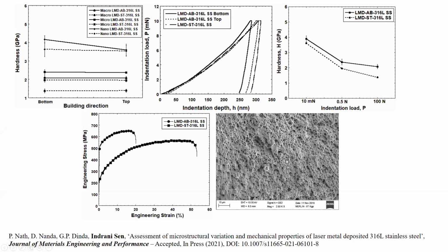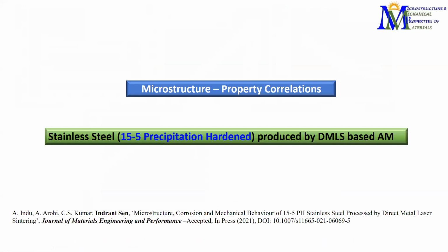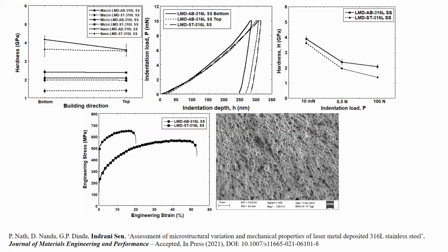Okay, this is a typical fractograph showing the dimples, which are evident for a ductile failure. So overall, what we understand from this study is that we can use the conventional heat treatment procedure, especially the solution treatment, to get rid of the microstructural inhomogeneity and end up having the optimized property requirement of high ductility and moderate strength, which is well within the limit that is being used for practice. Okay, the details can be found in this paper here.